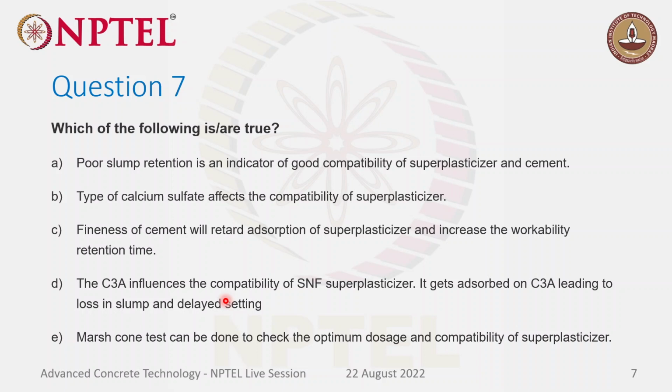And then coming to fineness of cement, fineness of cement will retard adsorption of superplasticizer and increase the workability retention time. So here they're saying if cement is very fine, will it retard the adsorption of SPs and increase the workability retention time? If cement is very fine, just think about it.